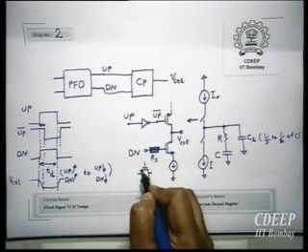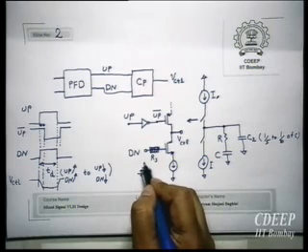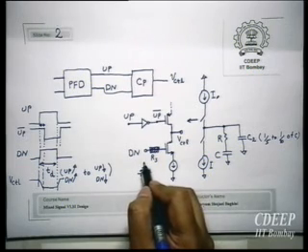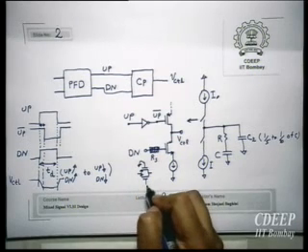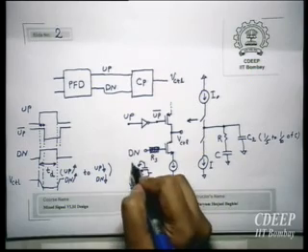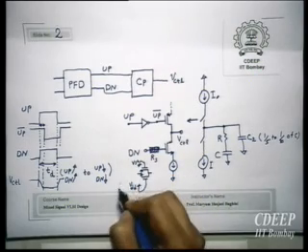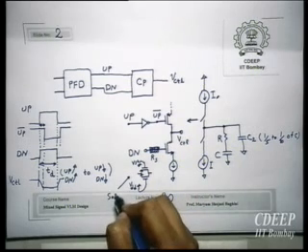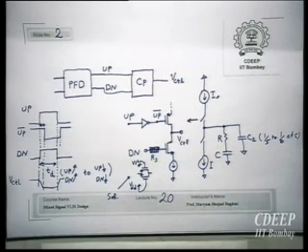So one is NMOS, one is PMOS. Therefore this is connected to ground or VSS, and this is connected to VDD. So this is one of the solutions. Essentially, this is one thing that you need to consider when you design: make the same delay from up and down till the switches.